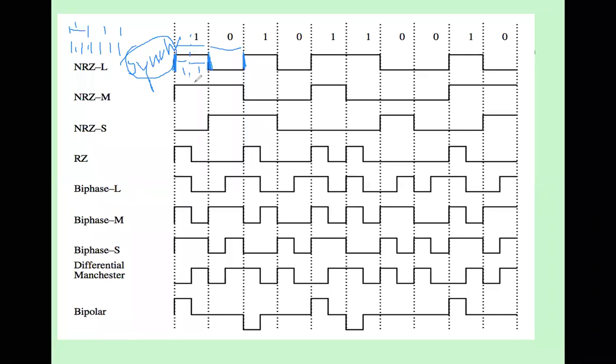And the second reason is the DC component. DC component means, whenever the signal is at zero, we say it is at zero, but actually there is some residual current, some residual voltage there. So it is not exactly zero. That's why that issue is called the DC component issue. So we have to take care of these two problems.